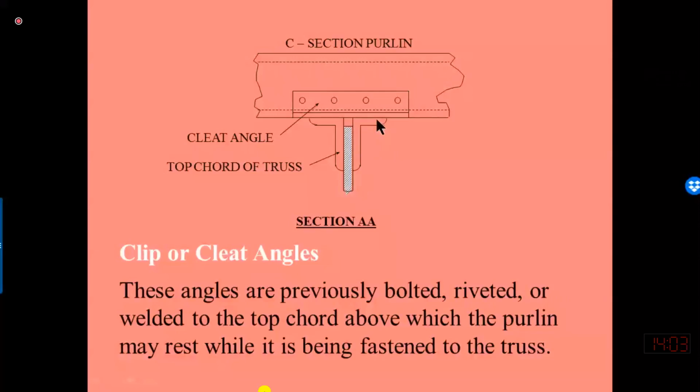So it means that for a larger width, the center of gravity will be away from this vertical leg, which will have a secondary effect. Secondary effect means that all the loads pass through the center of gravity, so they tend to produce a rotational effect. So in this case, the width of the angle section is limited to 102. 102 means around 4 inch. The vertical leg, the longer leg, may have any length, any dimension. It may be more than 102, but this shorter leg, which is supporting the roof sheeting, should be less than 102.